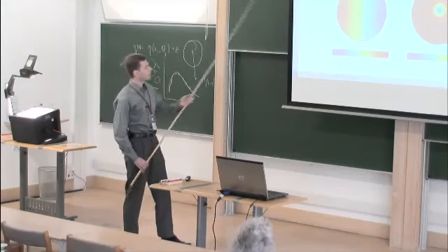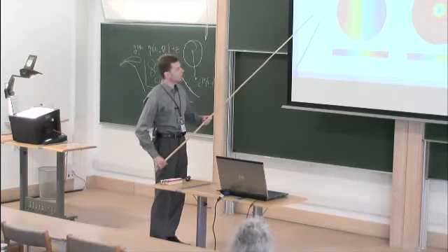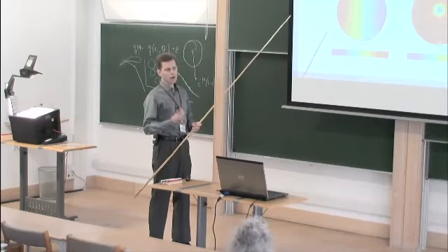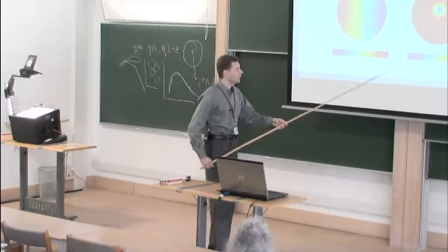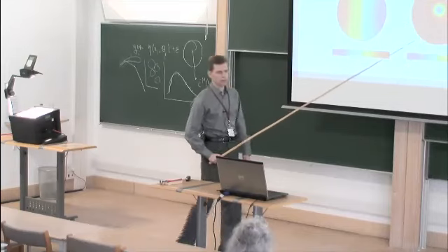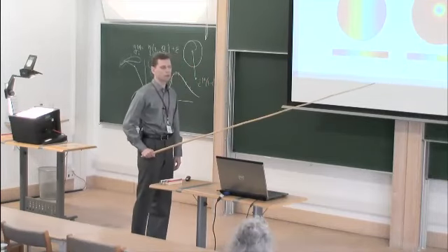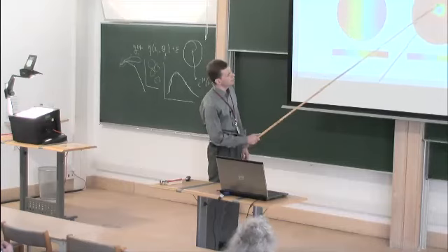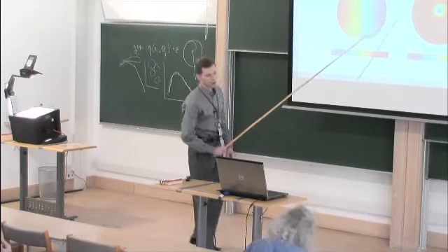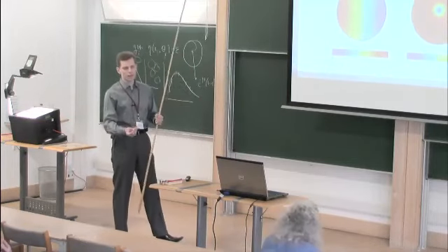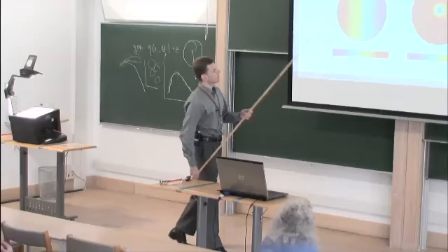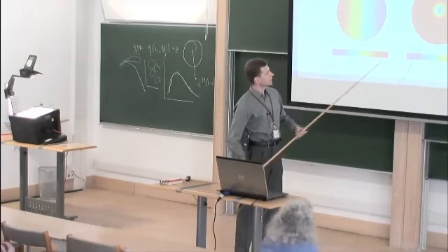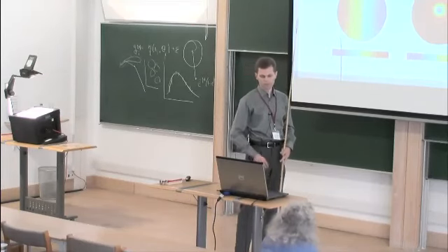Then, based on the measurements taken on the boundary, we try to reconstruct some electrical parameters within the interior. For example, the conductivity of the gas bubble and the oil are different, so we can build the image of what is going on inside the pipeline.